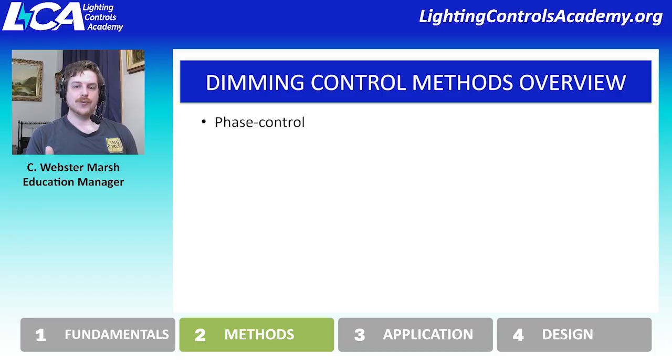So making sure that dimmable fixture that's phase controlled and the dimmer that it's being controlled by are compatible really makes sure that that lower part is optimal for the application, whereas the higher end tends to be not so concerning, although we do still see incompatibilities even at the full value, where the dimmer just for some reason creates a weird behavior in the fixture.